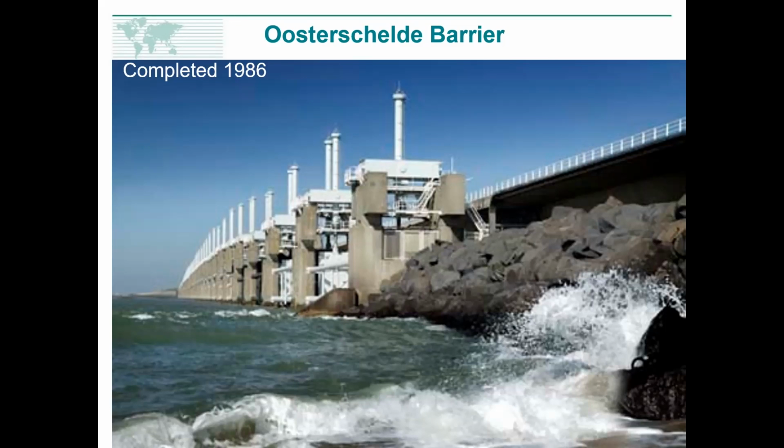and this is the Netherlands, and this is the Oosterschelde barrier. What you're looking at here is a storm surge barrier, the Eastern Scheldt storm surge barrier, and these are concrete caissons with gates to shut out storm surge when you've got a high surge in the North Sea. And these concrete caissons and their gates are actually founded on a hydraulically placed sandfill pad underneath them.